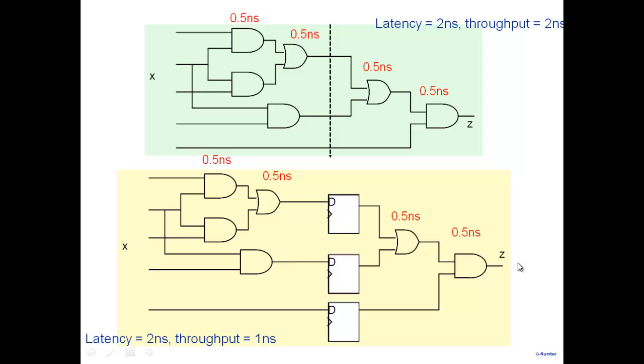It's the same clock which is running everywhere. So you can't do that. It will still run at 1.5 nanosecond. Okay, so you remember, everything is clocked. There's a set of registers here, a set of registers here, a set of registers here. So you're always going from one storage to the next storage. If you break it up here, you can easily see that from here to here, I have 1.5 nanosecond. I can't run my clock at 0.5 nanosecond.